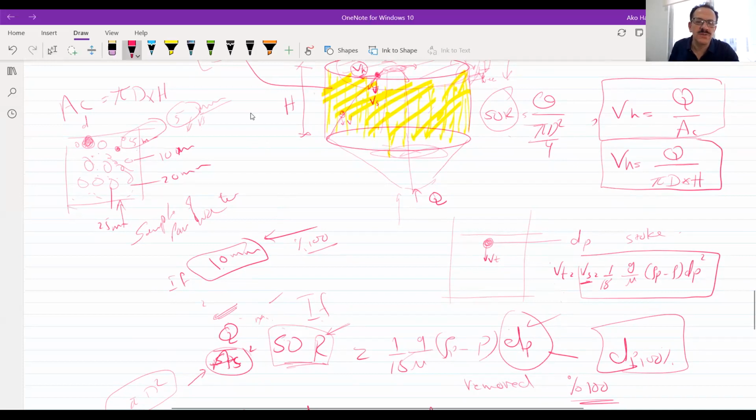The ratio will depend on the velocity. So if the particles of 10 millimeters give you a settling velocity, which means 100% will be removed, then that is the Vs of the 100%, and then we have to find, using the same equation, the settling velocity of particles having a diameter of 5. Then dividing that Vs by Vs naught, or Vs 100, will give you a ratio.